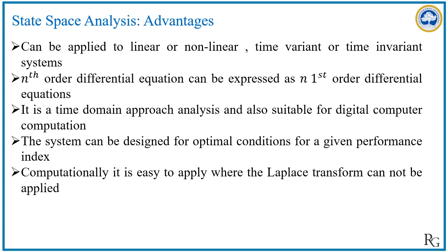The state space approach offers several important advantages over classical methods. First, it can be applied to a wider range of systems, whether they are linear, non-linear, time variant or time invariant. This makes it very flexible and powerful for modern control system design. Second, any nth order differential equation describing a system can be converted into n first order differential equations. So this makes the system easier to model, analyze and simulate.